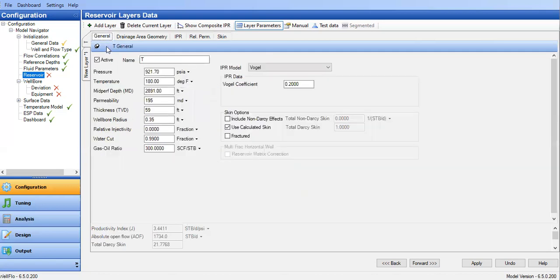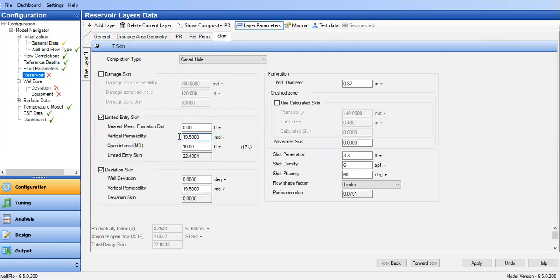In this case, we have uncertainty, of course, in permeability. That's why you need to correlate the permeability from well log with permeability from pressure build-up, for example, and permeability derived from the well performance, like in this equation. So in this case, I assume that the uncertainty belongs to the permeability. So let's adjust the permeability. Let's say the permeability is 250, and I change the vertical permeability to be 25, still maintaining the 10%.